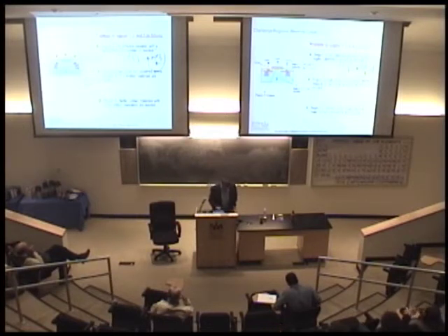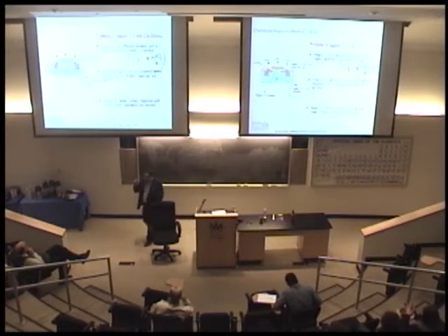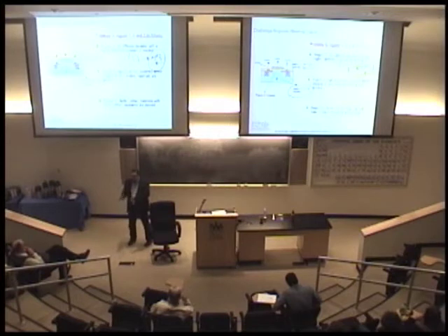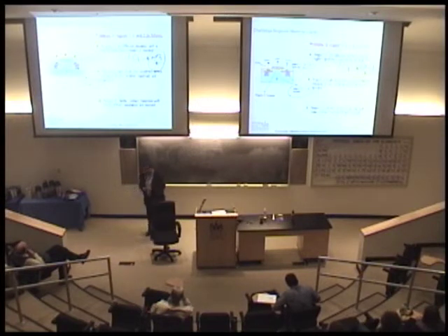And the other thing is region 2, dopants. These are the semiconductor regions. If you make this transistor smaller and smaller, you still want to keep the same number of dopants, okay? It was easy: if you have a big silicon, you can put in a lot of dopants. Dopants are arsenic or boron atoms you can put in to increase the conductivity. Now you want the same number of arsenic and boron atoms, but in a small silicon. What's going to happen? They get together, they cluster, okay? And it's not going to work like a nice conductive, semiconductive material, but it's going to be deactivated itself. So then you're going to have another breakdown for the transistor.